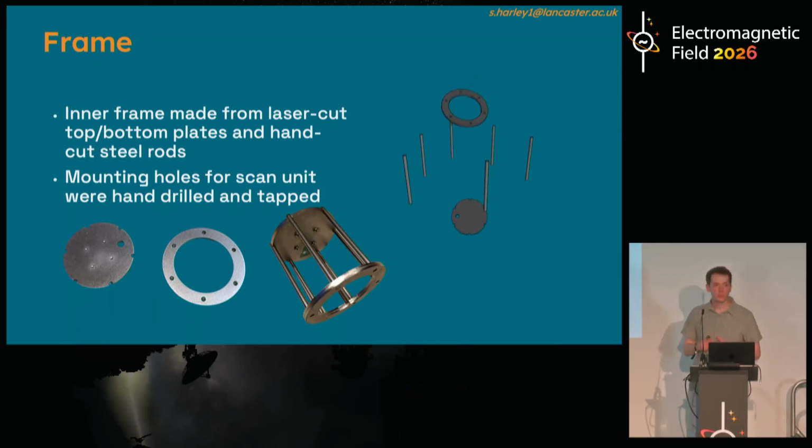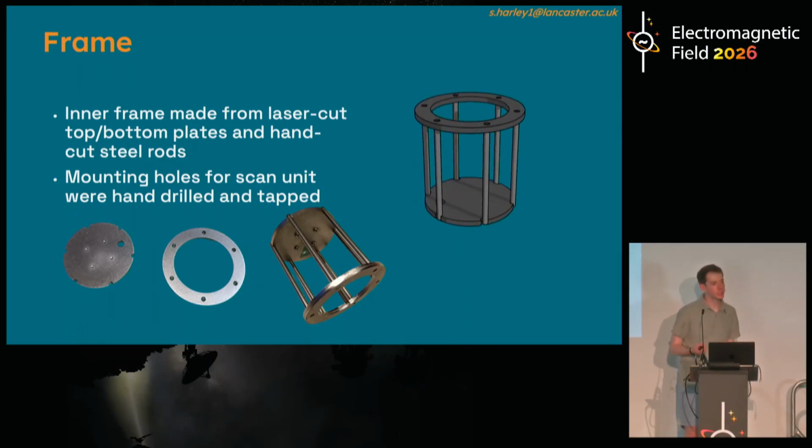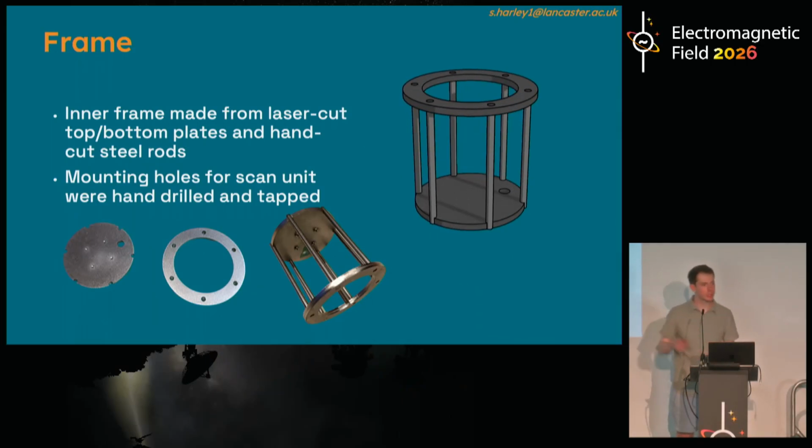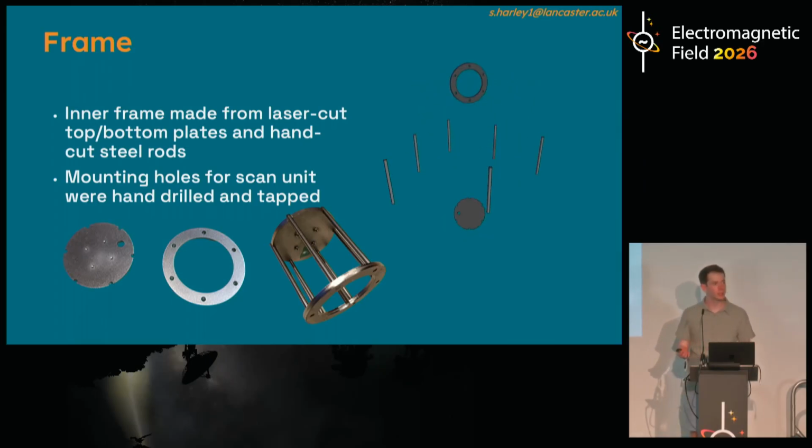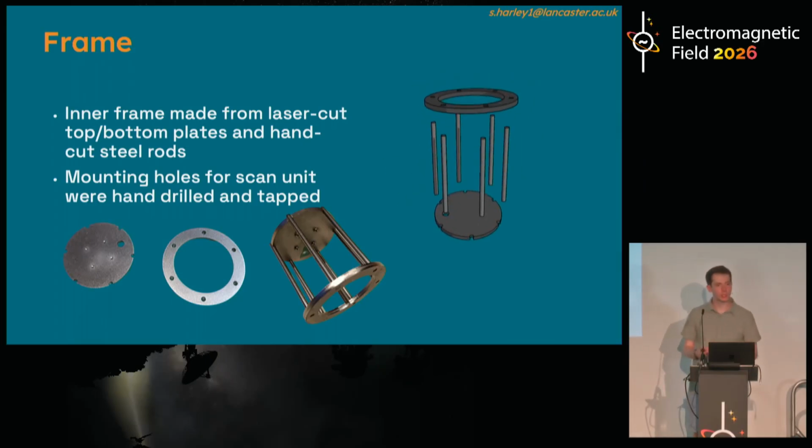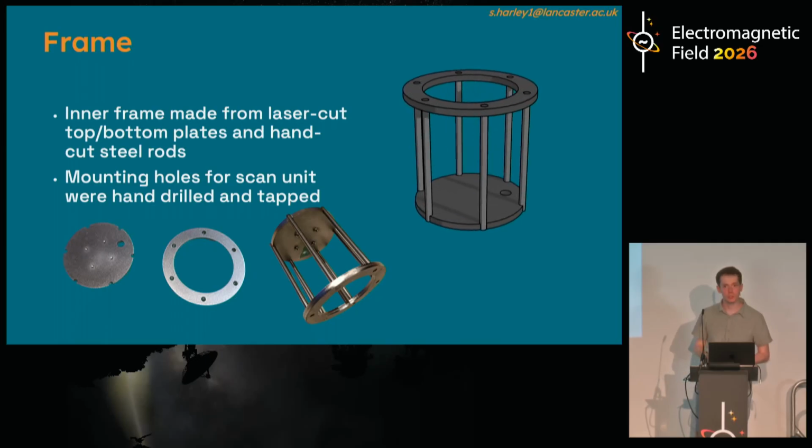And then the rods separating them are just hand-cut bar stock. And then the issue with just leaving it here is that if you ever take a steel structure and hit it with a hammer, it rings like a bell. So it's got a lot of resonances, which are actually amplifying vibrations at certain frequencies.